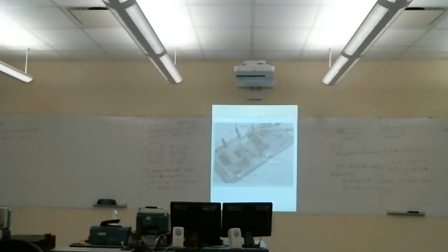So, again, this is an 8-bit register. Every bit in it corresponds to one of the pins. We'll have one 8-bit register for each port. Each bit in this register corresponds to one of our pins. The DIR 0 bit, if set to 0, makes that pin an input pin. And this is in the next figure.